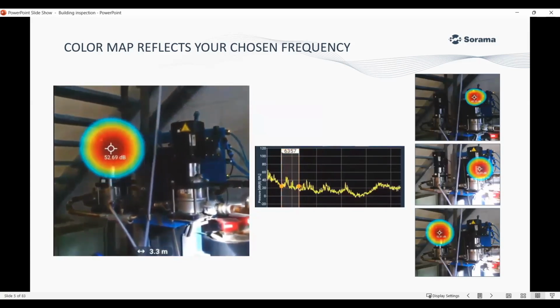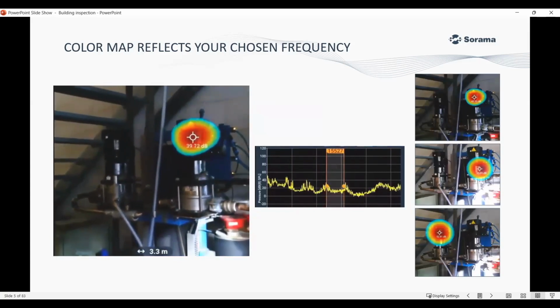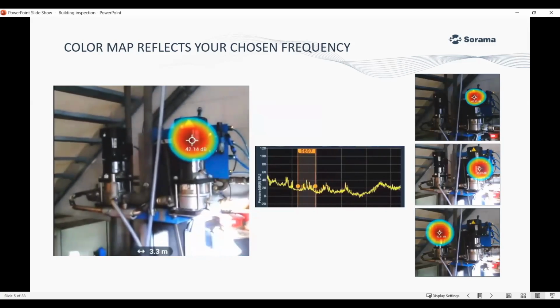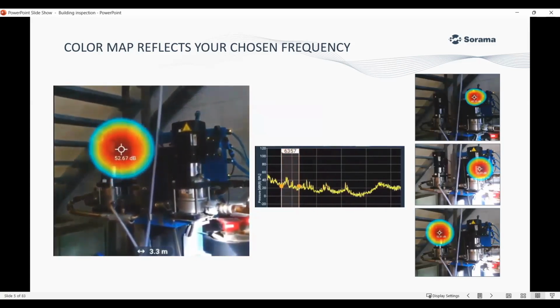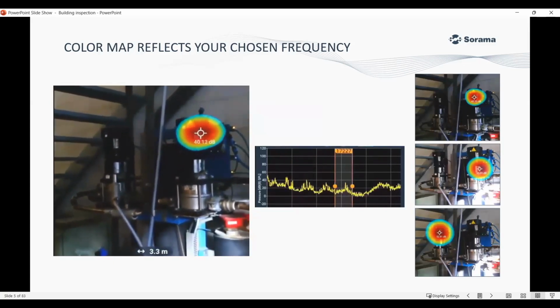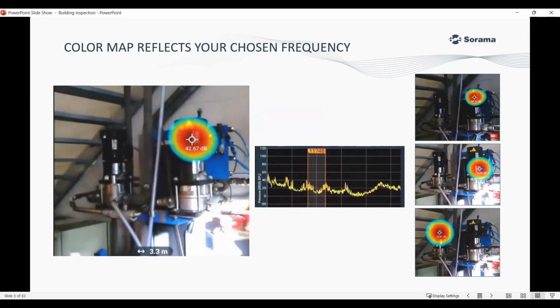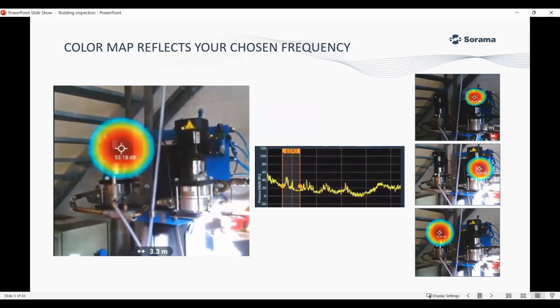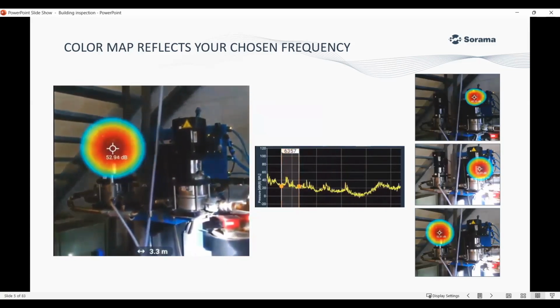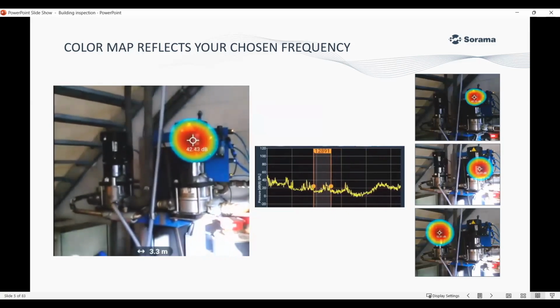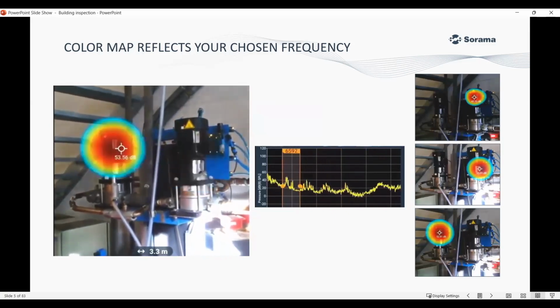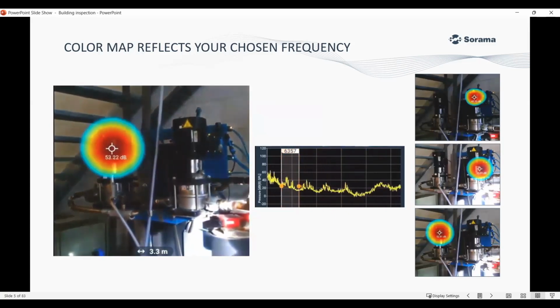When you have a small crack in a pipe and compressed air travels through it, it creates very high frequencies that people cannot hear, but you can pick them up with such technology. Because it's a different frequency, you can visualize very silent leaks in a still very loud environment.